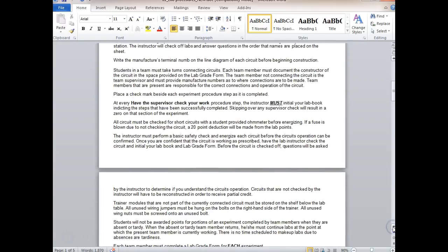I'll come back here and I'll perform a basic check, a safety check. The common side is L2. I'm going to check L2. If L2 goes where it's supposed to go, then there are no short circuits in the system, right? Y'all understand that?